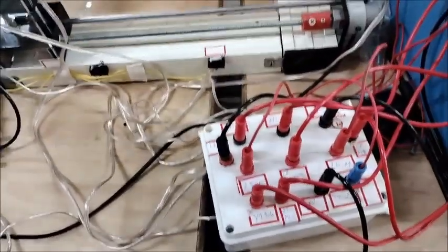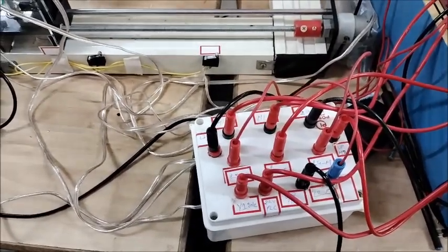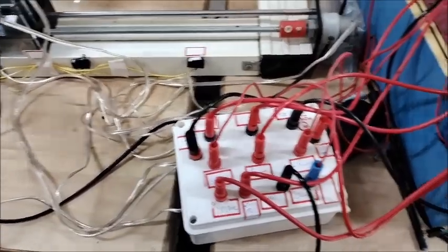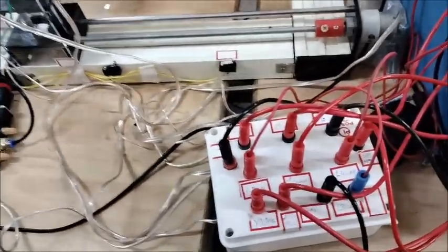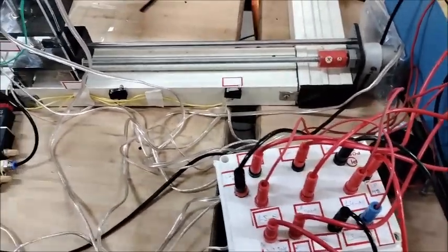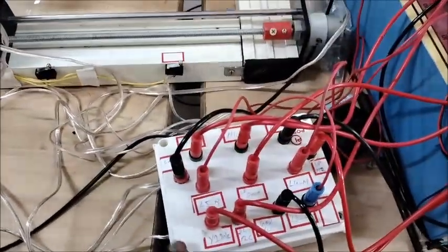And this is an interface box between the storage system and the PLC, because motor operating voltage is 12 volts and PLC operating voltage is 24 volts. So this interface module supplies power to the motor, because this module has an inbuilt 12 volt supply, and it also has limit switches. For easy connection, this interface module will help.